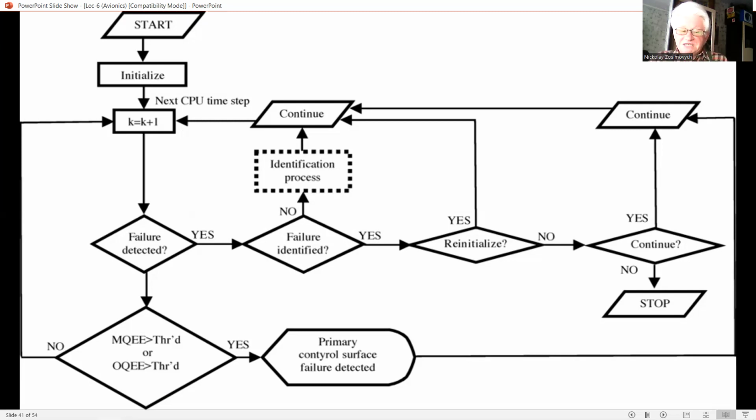The value of this disconnect threshold in conjunction with the failure detection and isolation algorithm determines the magnitude of the transient which the aircraft may experience as a result of the failed sensor being disconnected. There are thus two conflicting requirements. First, a low number of nuisance disconnections, and second, minimum transient on disconnecting a failed sensor.